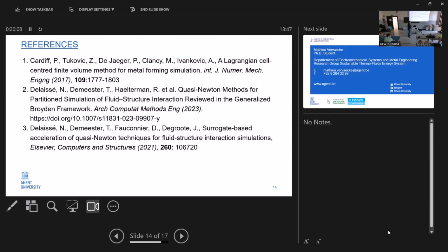Actually, our purpose is first to add the piezo-viscous effects, compressibility and the shear-thinning behavior of the lubricant. If that works fine, then we can be state of the art. But then the thermal part will be another step. I still have to do some rolling curves and look at thermal aspects, but that's some thermal effects in the lubricant itself. So probably that will be the first, and that's the exact reason for the big difference in the viscosity.